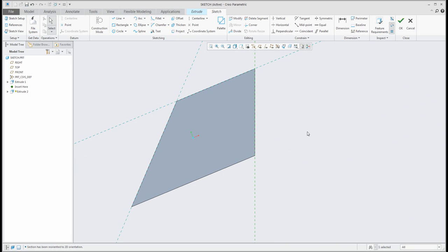And here is the question. If you delete some reference, I will delete some reference. And for example, later you would like to add this reference, because if you would like to create a line, you would like to directly snap to the existing lines. It's not a problem. You can select the reference window and you can select any line, surface or edge directly from 3D and add these features as the reference. And if you use these references in your sketch, the system will remember.